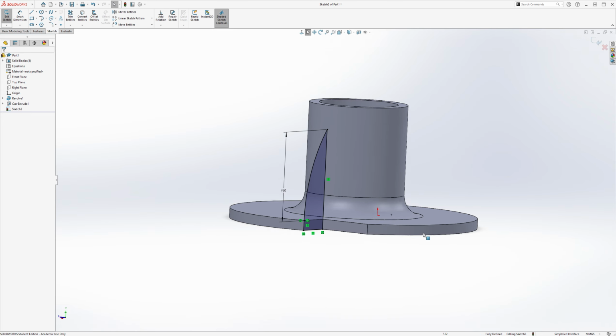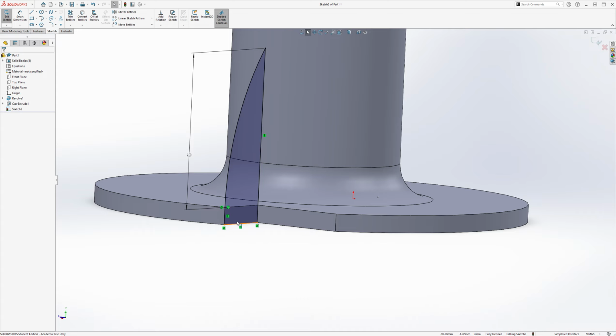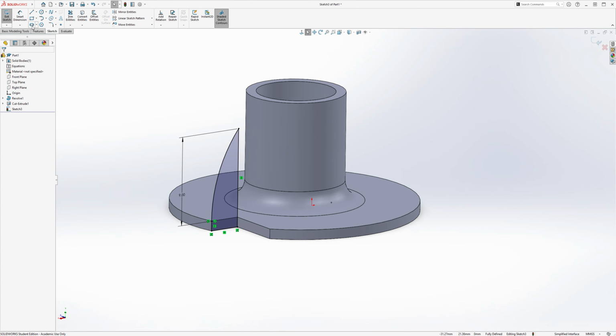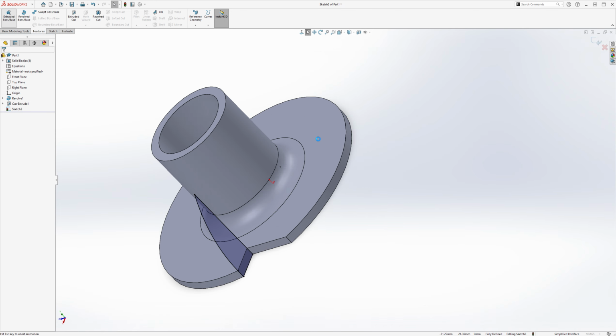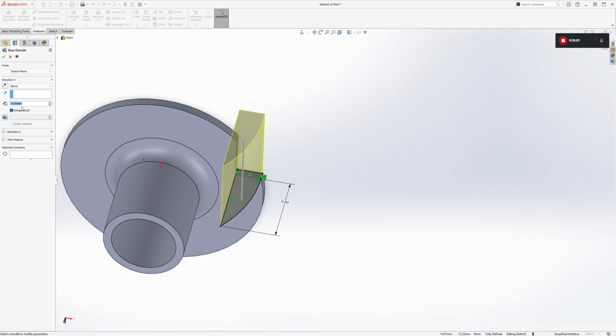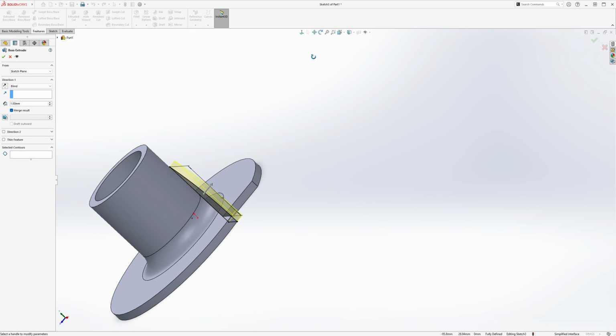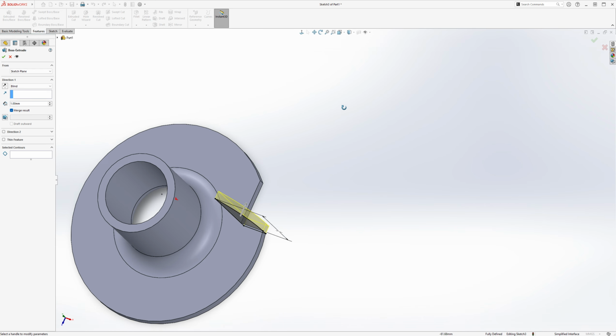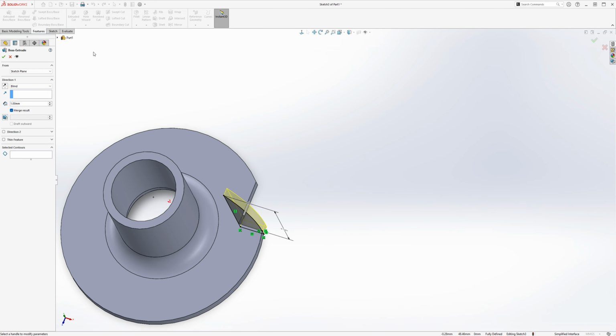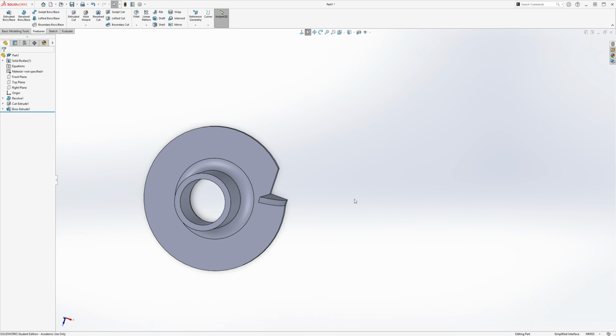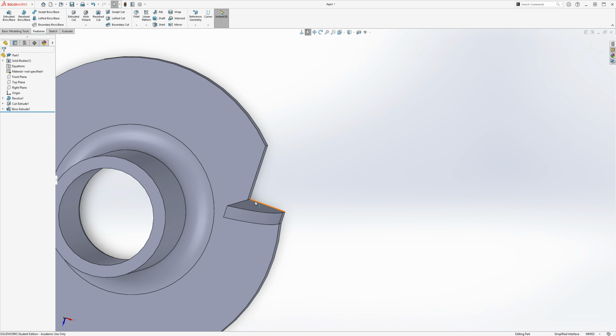And then it's going to be extruded by 1 millimeter to this side, not inwards, but outwards. So we're gonna go to features, extrude by space. We'll blind extrude it by 1 millimeter, like this. And we'll select OK. So now you've got your rectangular cut along with its extruded blade.